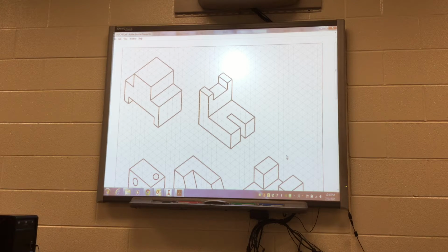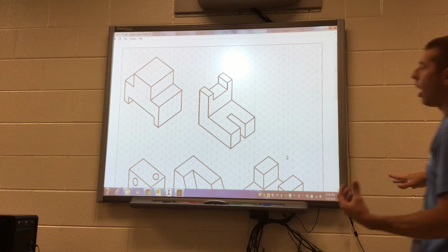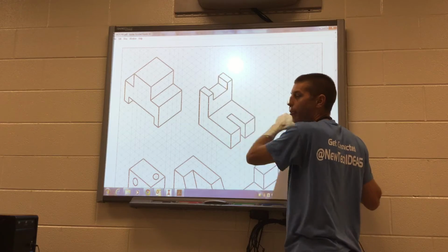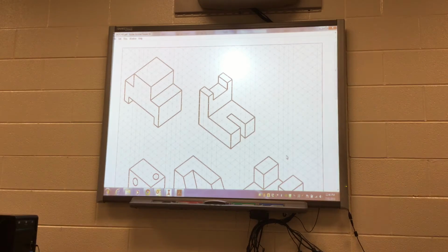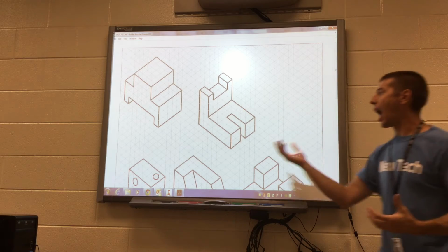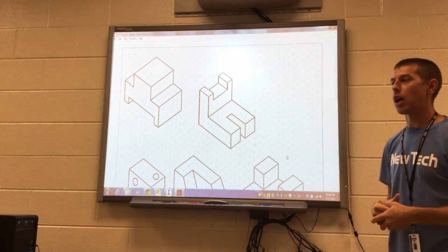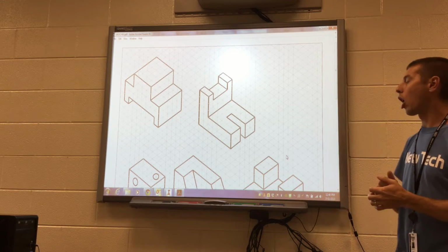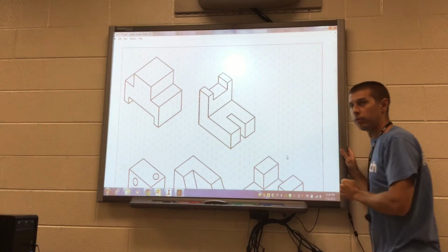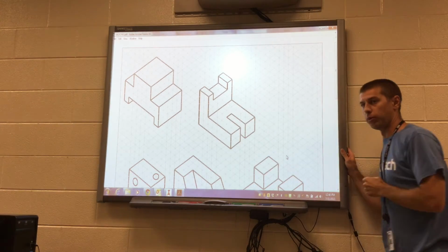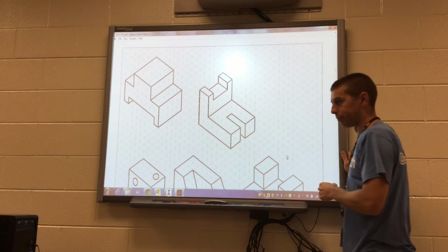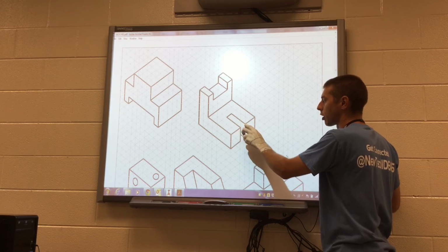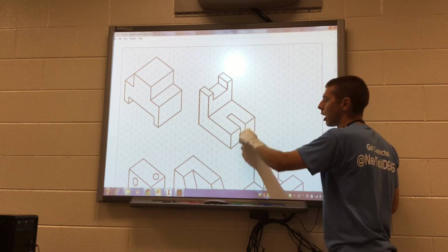And you do that by simply adding a new sketch. So once I get my L, you just simply click on the top and draw a rectangle, and then you can have the option to cut that away or subtract it out. Because with Inventor, you can either add things on or you can subtract or take things away. Inventor calls it join versus cut. And we'll talk about the difference of it. Once you do this one, then you need to do the same thing with this one. Draw a rectangle and then cut it out. Now, it doesn't matter which side you draw from. You can draw from this side right here and draw a rectangle and cut back, or you can draw this one right here and cut down.